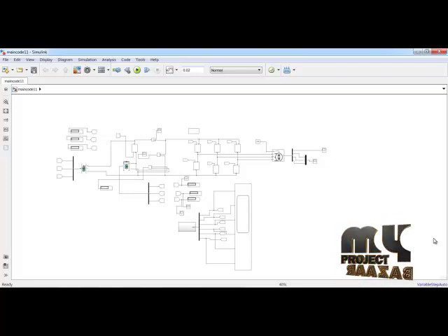Overall circuit. First we connect the supercapacitor and then the battery. After that, we connect to the inverter, which does the DC to AC conversion. In between, it connects to the DC to DC boost converter. After that, there is a pulse generation. We are using the S1, S2, S3, S4, S5, S6 switches in the inverter model. So three phases, and then it connects to the BLDC motor. This is a permanent magnet synchronous motor.